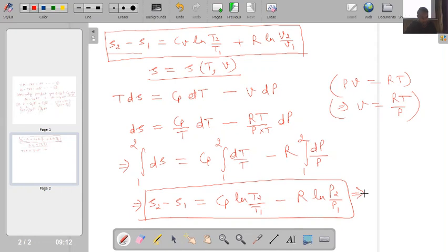Now the important point is, here you can see that entropy is becoming a function of temperature and pressure. Okay, so one interesting thing to note over here is that we have seen in the previous lecture that internal energy and enthalpy of a calorically perfect gas are nothing but the sole function of temperature, whereas the entropy of a calorically perfect gas does not follow the same behavior. So in place of only a sole function of temperature, it is actually a function of at least two independent intensive properties. So that is what we have done over here.